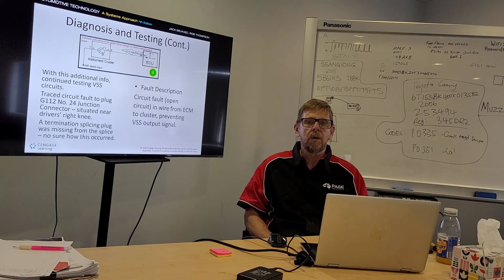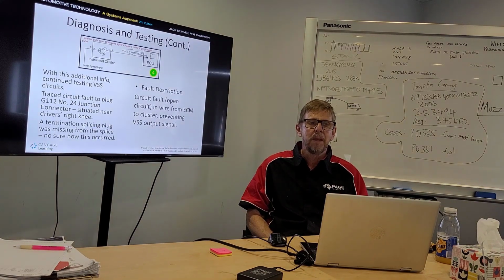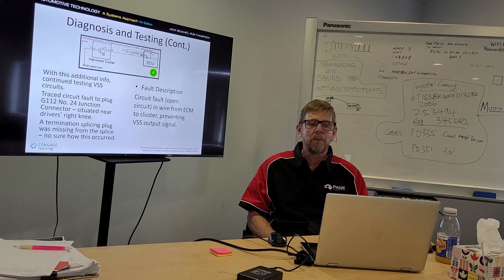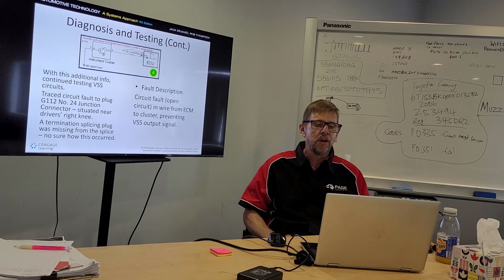And we couldn't buy a new splice plug because it had to be bought with a whole wiring harness. I think I bridged all the terminals that were left open, and everything worked fine. And I think later on we bought a second-hand plug, and we were able to fix that problem and continue. But that was a very tricky problem, and it affected really the traction control unit and probably other things as well.